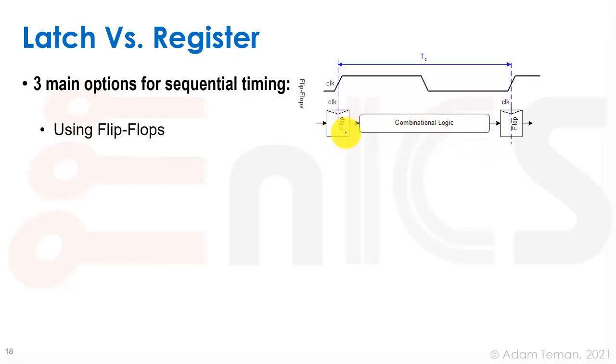There are going to be several flip-flops or mini flip-flops that are going to be the launching flip-flops, the start points, and there are going to be a whole set of other flip-flops at the end point. There are different paths between this set of flip-flops at the beginning, this set of flip-flops at the end. There can also be feedback loops because a flip-flop can belong to both sets, and this is going to be how we're going to clock them. We're going to sample everything at the first flip-flop and sample it again at the following flip-flop. And since the clock period is set according to the worst case delay, the longest path that goes through these flip-flops, we make sure there are no races between the data. Everything is synchronized by the clock.